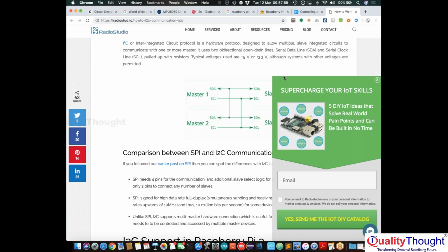When an obstacle is very nearby, somewhere around 10 centimeters, the range of the ultrasonic sensor is from 10 to 100 centimeters, so I can easily identify an object. If it is closing in, I can stop the vehicle also. All those alerts can be done at my side. We'll try the camera first.